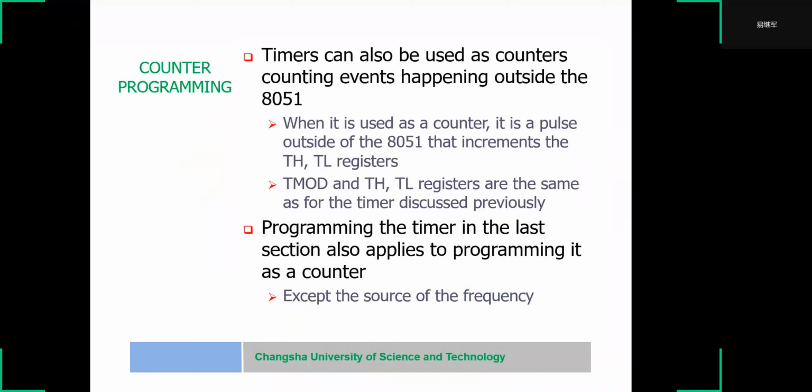Next, I introduce the timer used as a counter. Timer can also be used as a counter, counting events happening outside the 8051. When it is used as a counter, it is a pulse outside of the 8051 that increments the TH, TL register.